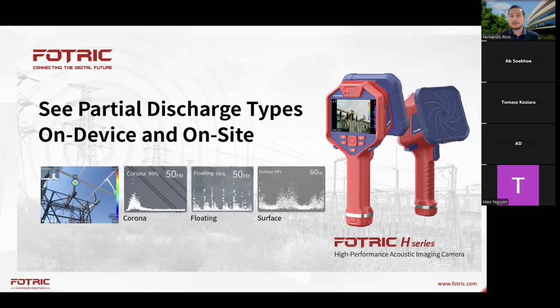And if you ask me, I've been to many substations, and a lot of people say, yeah, that's corona. That's fine. That's normal. They would only care if they are identifying arcing or tracking. So I've also seen reports made with other acoustic cameras from competing brands where the picture is processed and then the report says the image or the data is inconclusive. It is recommended that you take more data. So you pretty much drove for 2 hours to visit a substation. You came back to the office just to realize that the data you captured was not good enough.